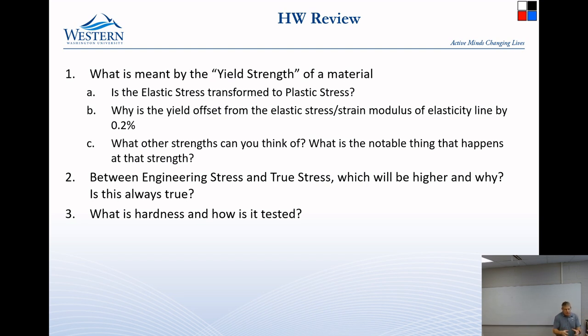I like this answer a little bit better, because what happens when you let go? What happens when you let go? So if I deform something and then I let go. After the point of plastic deformation, if I bend it, you'll almost see a similar elastic modulus, but you're going to have an offset in that strain. So now it's going to be permanently deformed, say, 0.2 millimeters off from what it normally would be. But you'll notice if you start to apply stress to it again, you'll have a similar elastic modulus, where it'll have a similar slope. That's the best way I can describe it.